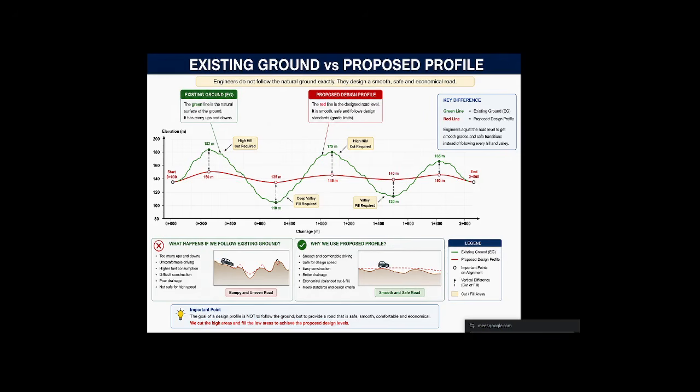Now the horizontal distance is 100 meter. Now we don't rise it, we fall it by 5 meter, and now I have to give the grade. Then how much grade do we give? First, sir, the grade percentage is vertical height divided by horizontal distance multiplied by 100. Right, sir? Right.